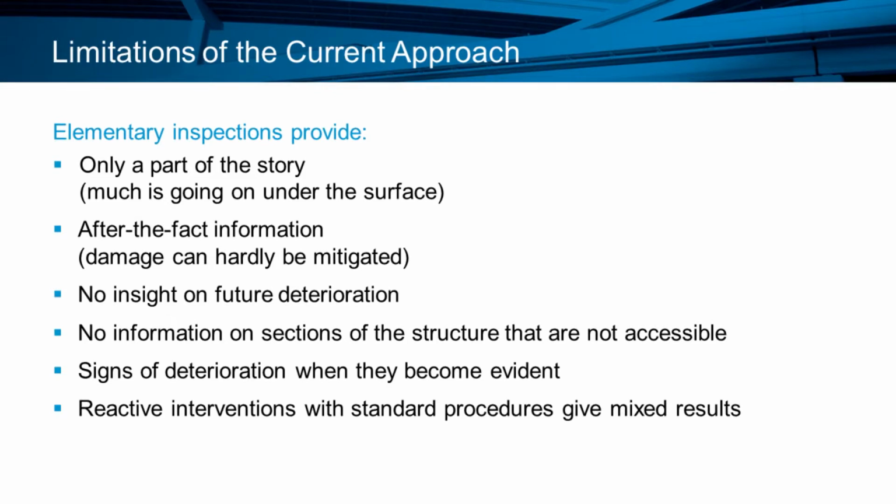What we'd like to do would be to see things coming before the damage is done in order to optimize the repairs. These inspection approaches have some limitations, and the main one is that we don't see what's inside the concrete just by visual inspection. In some cases NDT is performed, that's better. Sampling can be performed as well, that's even better. But if we just rely on visual inspection, we don't see what's going on inside the concrete, and we don't know what to expect and when to expect it.